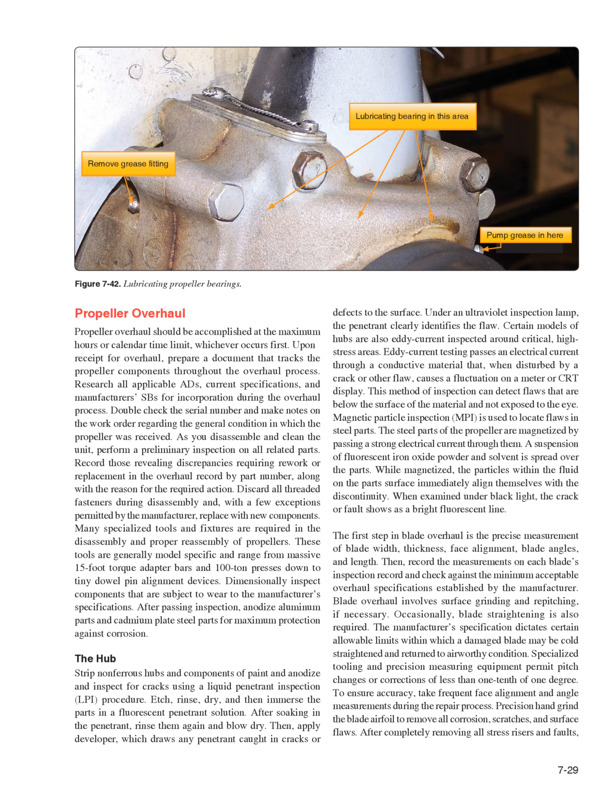Then, apply developer, which draws any penetrant caught in cracks or defects to the surface. Under an ultraviolet inspection lamp, the penetrant clearly identifies the flaw.